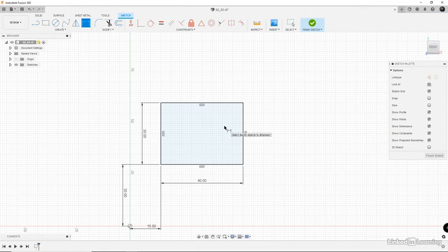Now let's go ahead and create another line and see what other kind of constraints we can automatically create. Now you see that this snapped to the middle of the line, or the midpoint, and that triangle icon right there is the midpoint icon for constraints.